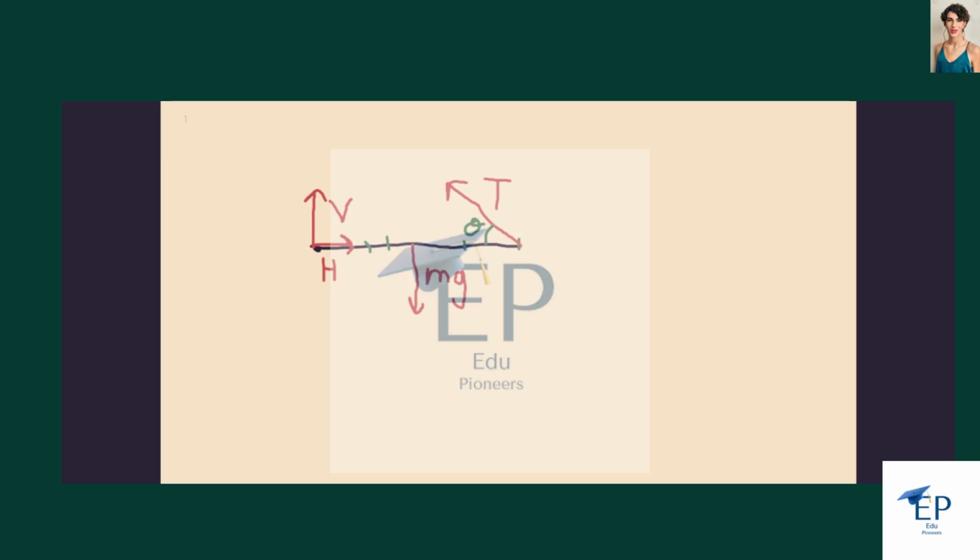For part A, we're asked about the strength of the cable, so we're looking for this tension T. And what I'm going to recommend doing to find that is, since we've got these other unknown forces over here that we don't really want to deal with right now, let's use the condition that the sum of the torques around an axis is 0, and I'll pick the hinge to be my axis, because that way both the vertical and horizontal components of the force at the hinge produce no torque. So that simplifies our torque equation. Sum of torques about that axis equals 0.